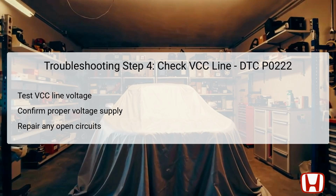the open circuit. This could involve replacing wiring or checking connections to ensure they're secure and free from any corrosion or damage. Resolving issues with the VCC line is imperative, as it provides the sensor with the voltage necessary for sending accurate data to the PCM. Without a proper supply from the VCC line, the system cannot maintain optimal engine operation.